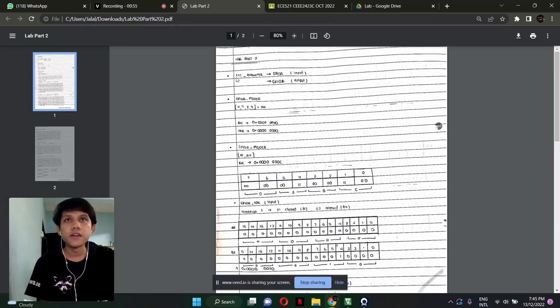First we set RCC AHB1ENR for GPIOA and GPIOB, port A as the input and port B as the output. Then we set GPIOB MODER, port B, to enable the port output 4, 5, A, 8 and 9 to turn on the pins. This is like question number 1: BIC 0x000F0F00 and ORR 0x00050500, same as the previous question.